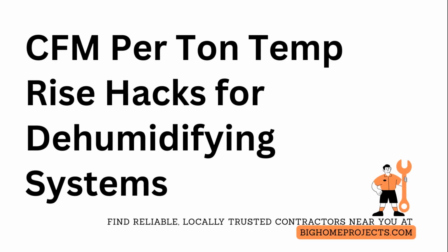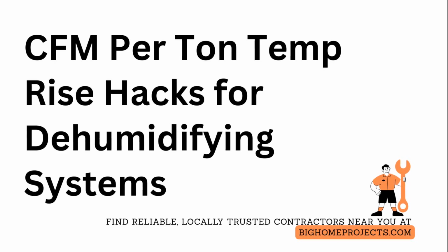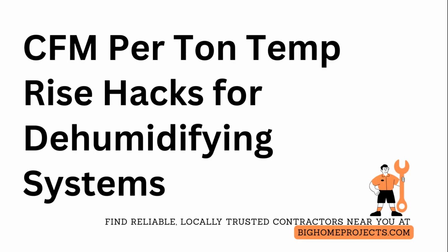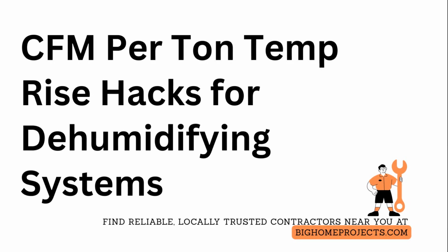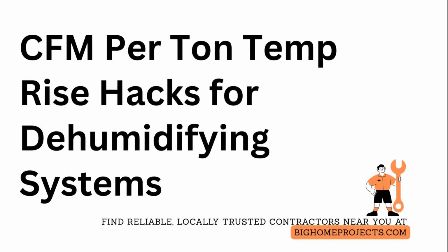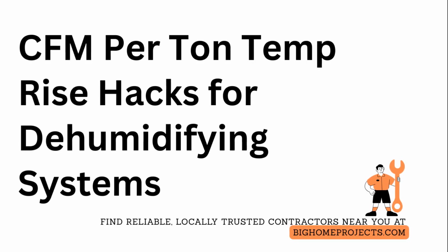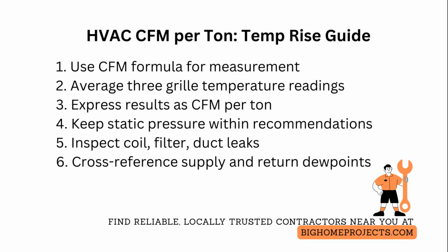The HVAC temperature rise formula for measuring airflow CFM reveals how many cubic feet per minute your system actually moves and directly predicts comfort and moisture control. Learn how to interpret CFM per ton for precise humidity and cooling balance. Use the temperature rise formula.